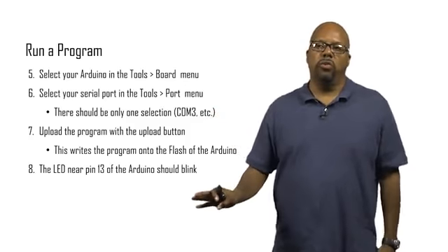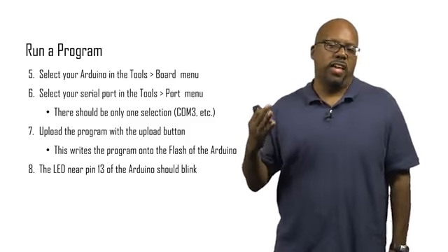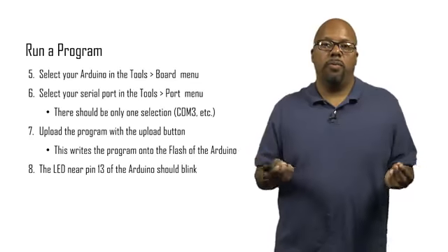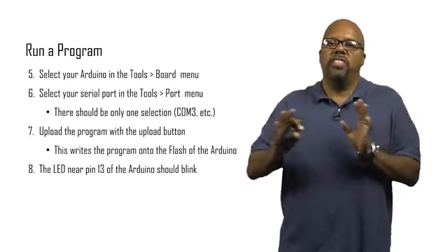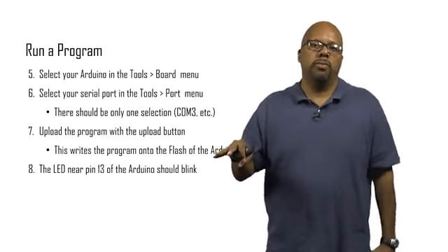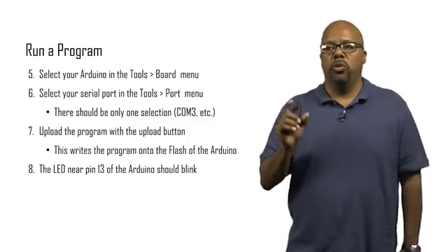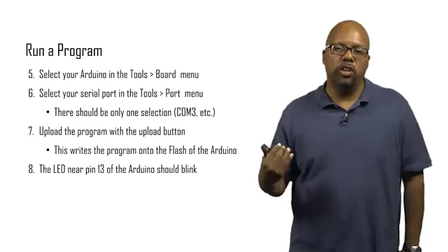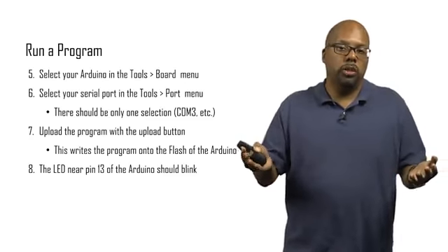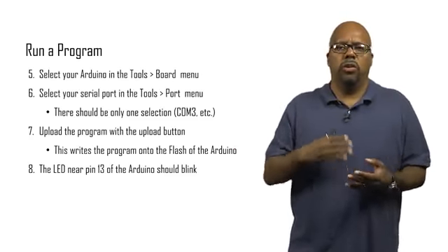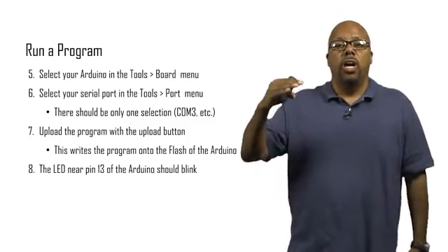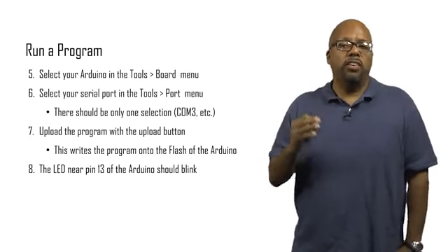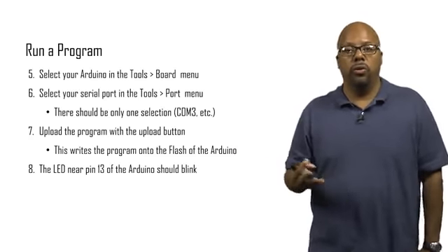To get to the point where you run the code, first make sure the machine has recognized your Arduino correctly. You may not have to do this. If you're lucky, as soon as you plug it in, your OS will detect it and everything will be fine. But here are some checks you typically do before you program. First, select your Arduino board in the Tools, Board menu. It lists a bunch of Arduino boards. Arduino Uno is typically what you're going to be using, but there are many variants: Arduino LilyPad, Arduino Duemilanove, and so on. Usually it detects the board automatically and highlights the one you're using, but just in case it didn't, select the one you're using, Arduino Uno, let's say.